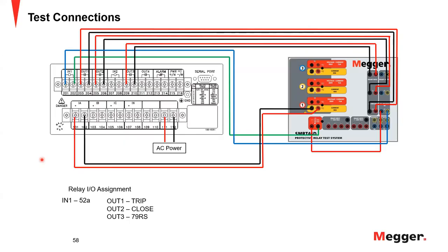Thanks. So our next question is going to be for Sughosh. Do some test templates exist for reclosing tests in the RTMS? Yes. Like you already saw what Mike showed, we have the state sequencer feature that by default is set up for a 2-shot lockout testing. And we also have these test templates that are embedded in the relay test plans. Based on the settings you read for the 79 element, it is going to automatically configure the template for your testing. So yes, we do have the templates.